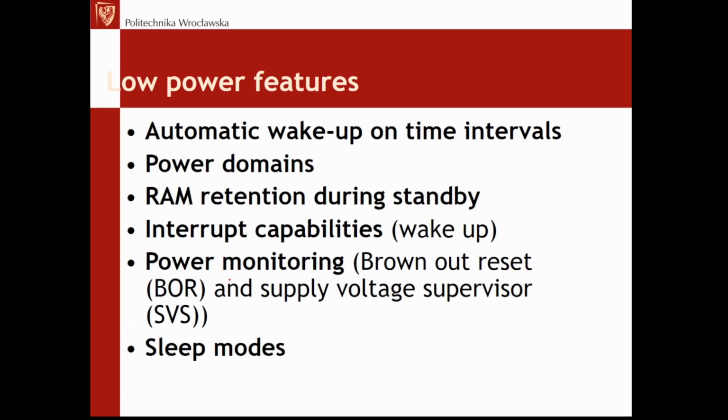And if the microcontroller is missing the majority of those features, then you simply should choose another one that includes them. So the feature that I find very useful is first of all automatic wake up on a time interval. It's really a must-have today. So those two features, I put two lines showing the same.